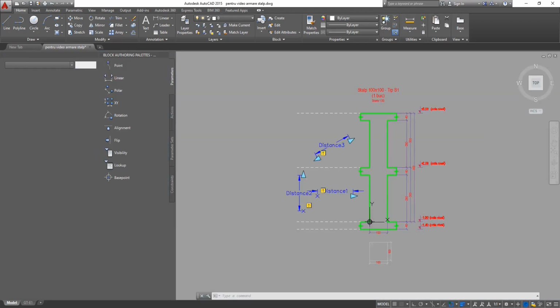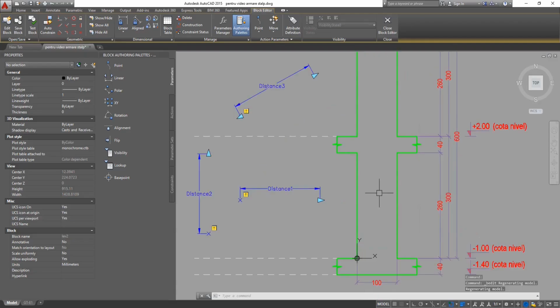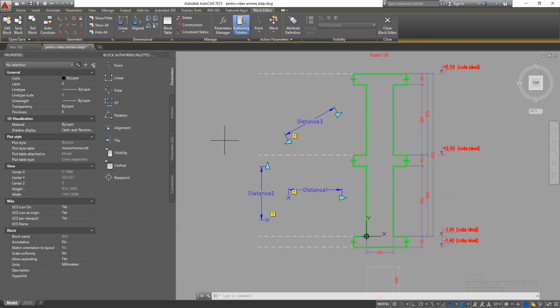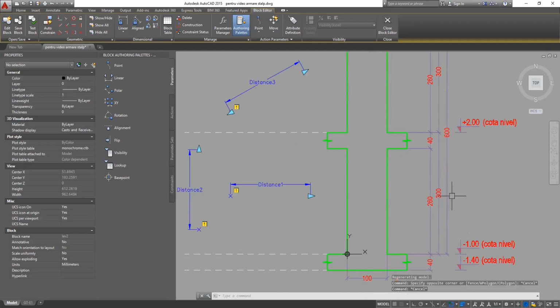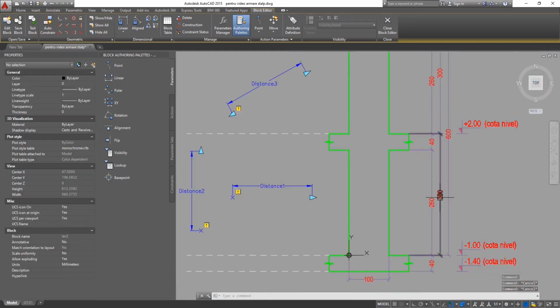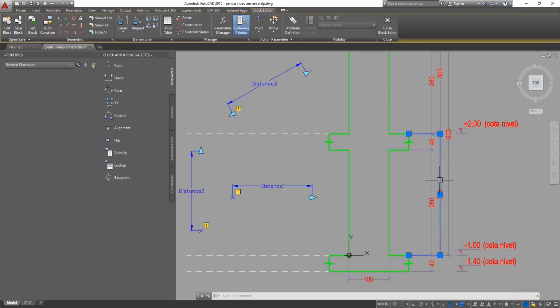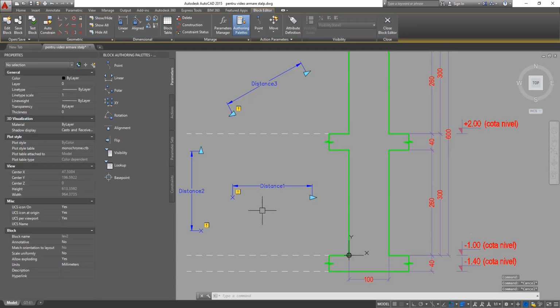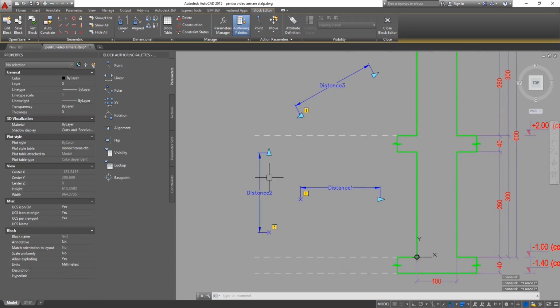okay, we're just going to enter again. Let's say we want to manipulate the height of the first span, the height of the first column on the first level. So we already have it dimensioned, it's 300 centimeters. If we want to see this value outside the dynamic block, the block will not read this dimension, it will actually read the length of the constructed parameter that will represent the height of the level. Okay, I hope it's clear by now.